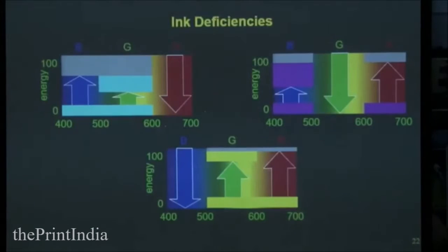So if you want to measure cyan ink, whatever you want to measure, it should appear black to the instrument. Like when we read a book, we have black text on white paper. Good contrast, that is why we are able to read it. If it's light yellow color, there is no contrast, so you cannot read the text properly. Okay. So the same thing here, when you measure the ink, that ink should look black to the densitometer, then only it can measure it properly.